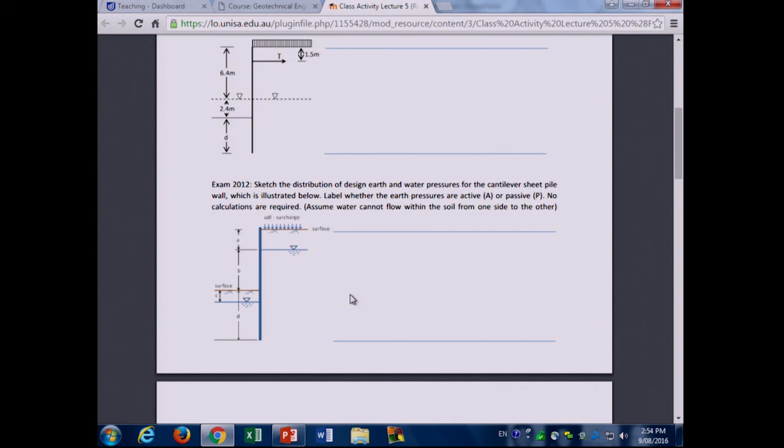But when you translate it from the vertical stress diagram to the horizontal stress diagram, it should be smaller, by K. But then that changes the slope, even though the unit weight's the same. Yeah, that changes the slope. It's not related to unit weight, right? I thought it was Ka times unit weight. That would be the slope, if there is no c. So for the vertical stress diagram, the slope is just the unit weight, but for the horizontal stress, it's the K parameter times the unit weight.